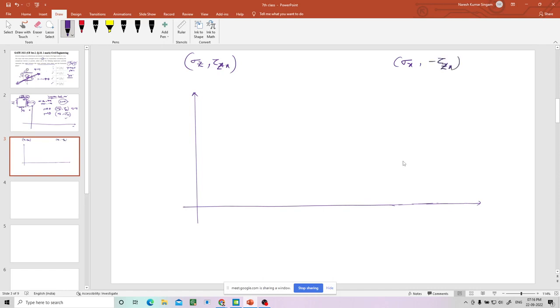Here if you see, the magnitude is the same, only the sign is different. Suppose it is 10 comma 5, and the other, let us say 7, is again 5 but minus 5, that's it. It is just two numbers. As this is tau and this is sigma, let's first plot this point, sigma z somewhere here on the sigma axis and tau zx somewhere here.